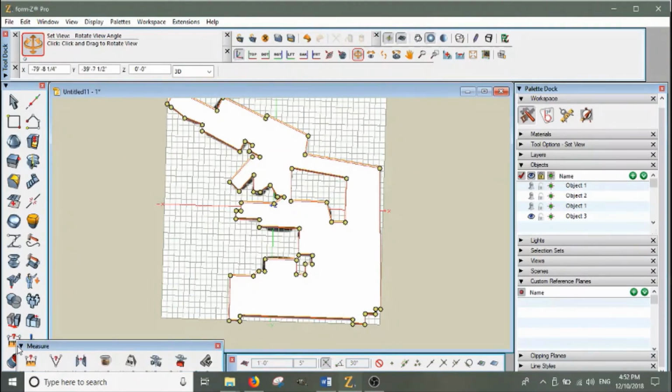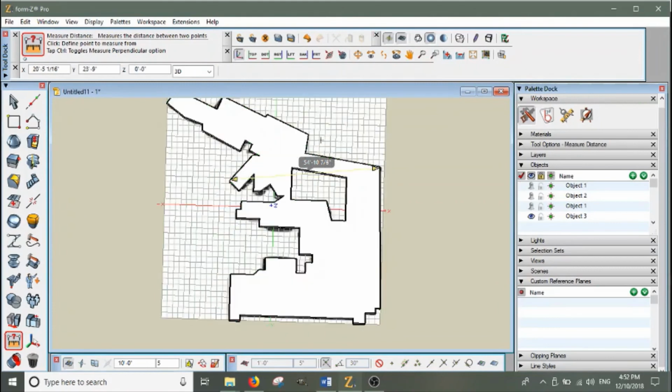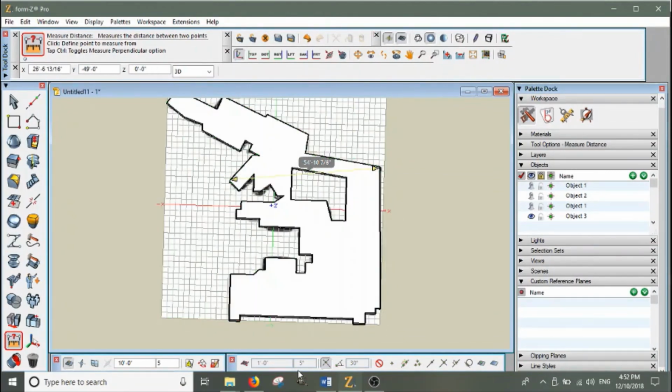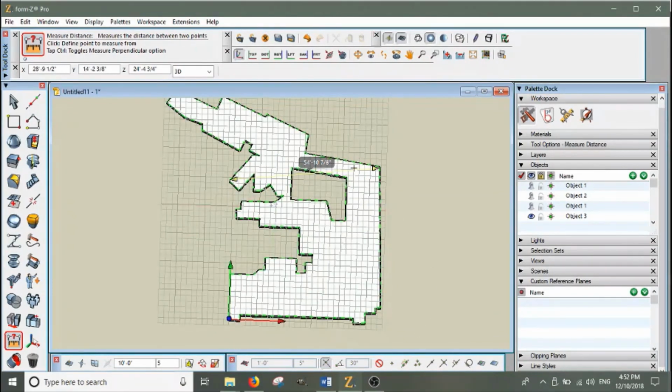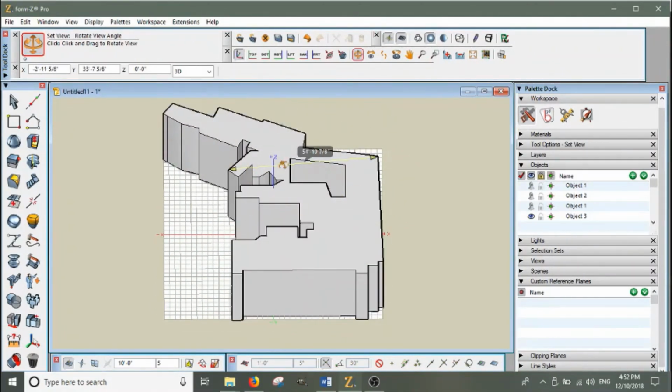But you can also use the nice measure tool here, the simple ruler that allows you to measure the extents of objects within this feature. Now, one thing I will note, however, is that when you're doing this, it's important to pay attention to what snap features are active, so that way you know what you are or are not actually pressing. Because it's very easy that you might be trying to measure across this flat surface, but you might end up actually measuring the diameter from one corner